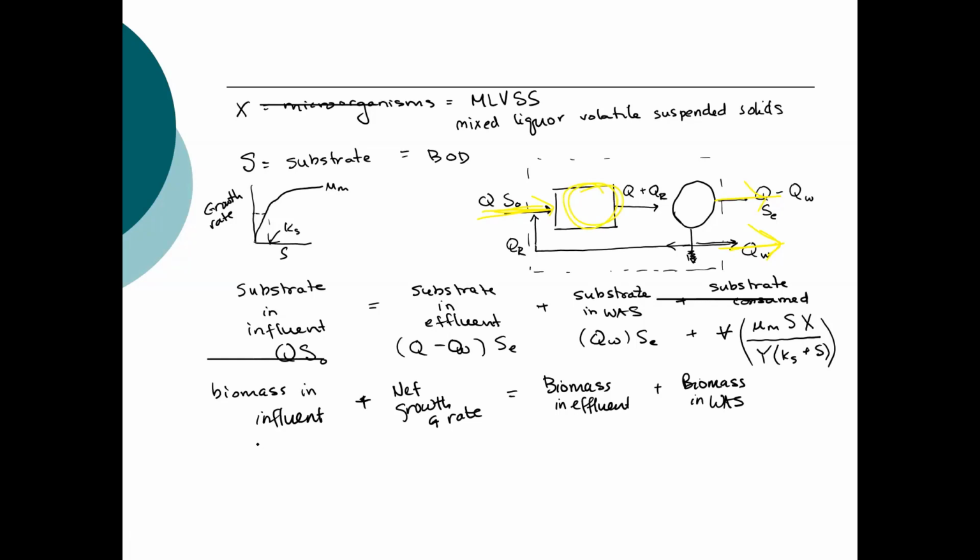And this is equal to Q times X naught. This growth rate is modeled with the equation here, volume times mu sub m S X over K sub s, and I'm not deriving these equations, minus kd times X. K sub d is the endogenous decay constant.